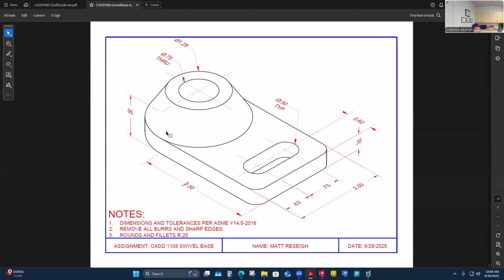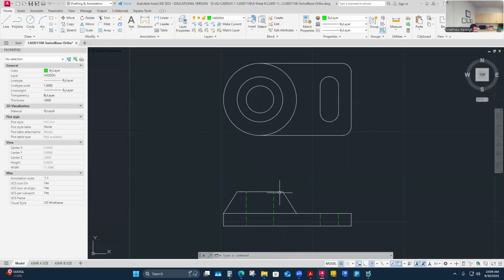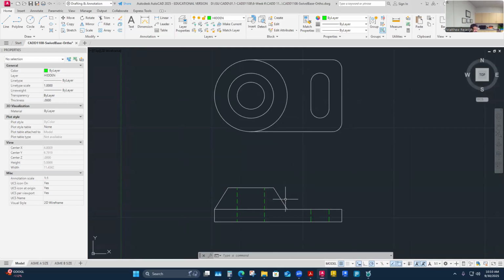This might be something that I would come back with some weld symbols and say how these two parts are joined, but maybe I need some more details on whether this is a flat piece that's rolled into a cone, or is it actually machined out of the whole diameter, or 3D printed, maybe something that's this whole diameter and then it's just kind of printed like I showed in the front view here, like it's kind of thick. Anyway, I don't know. It's a little bit vague. I remember drawing this one before and thinking there's some undefined stuff, but with what I've been given, this is how I'm going to draw it, I think.